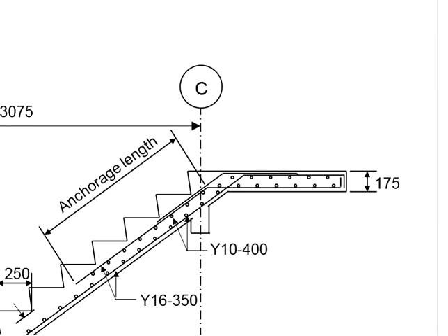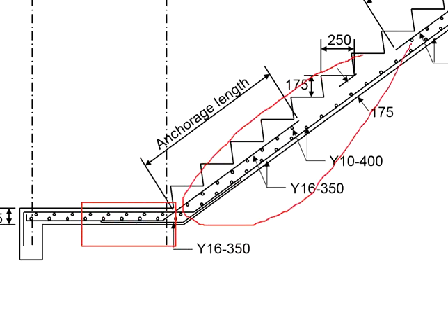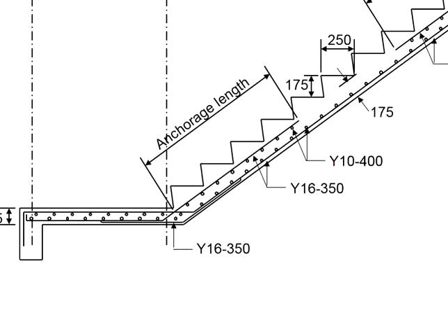Bear in mind that this reinforcement bar is very important to prevent the hinging failure due to the arrangement of the reinforcement bars here. The same principles apply to this joint here. When you have a horizontal landing joining with the diagonal flights, we adopt the same principle.